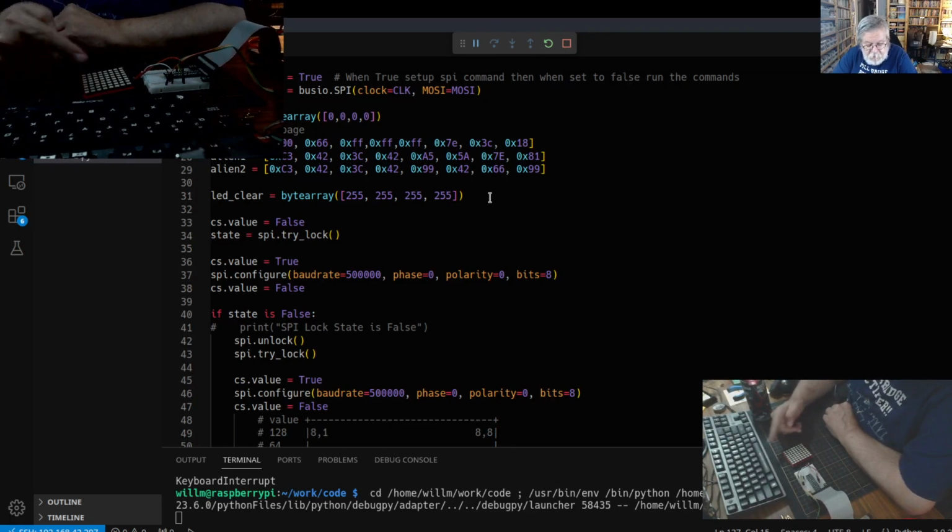Now, adding them together gets you combinations of rows turned on. So in theory, 128, because that's 64 plus 32 plus 16 plus 8 plus 4 plus 2 plus 1, will light all the matrix. But once you go past 128 on the row setter register, it gets weird.